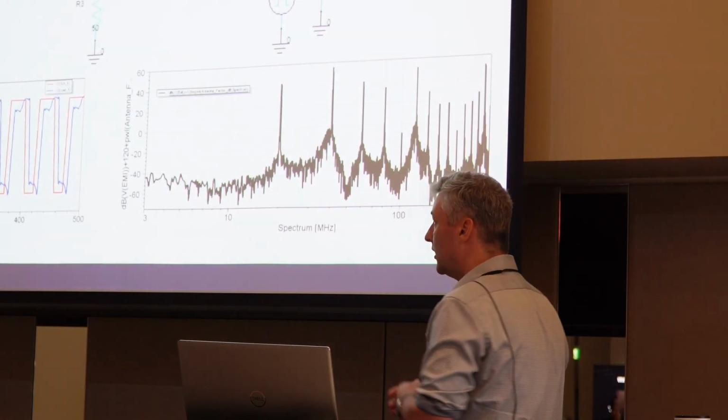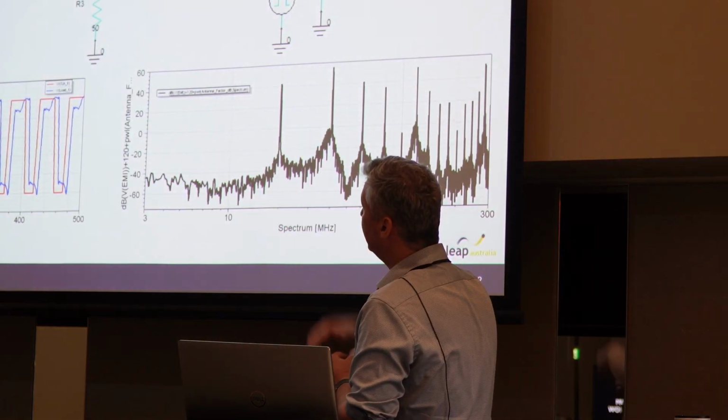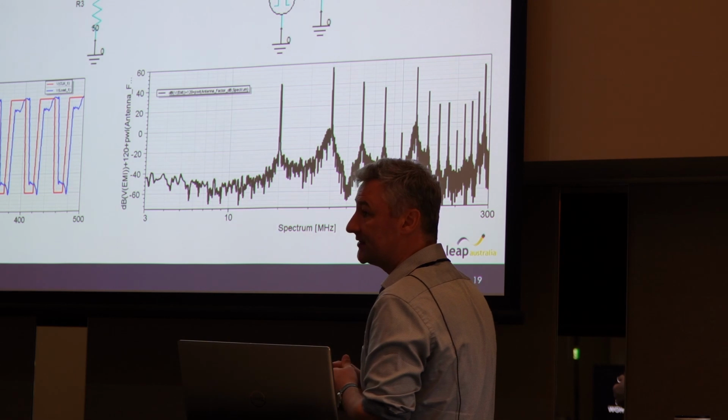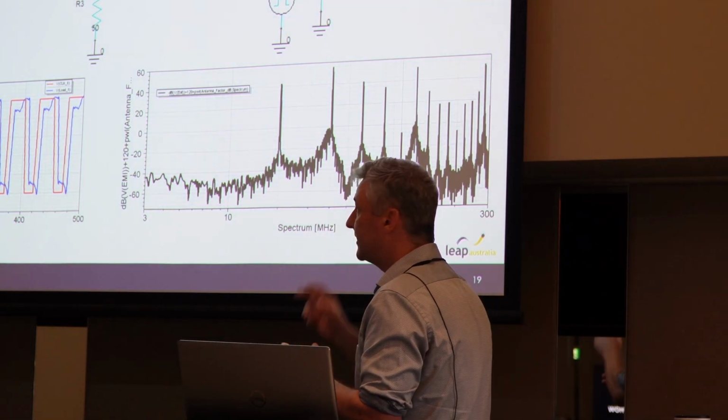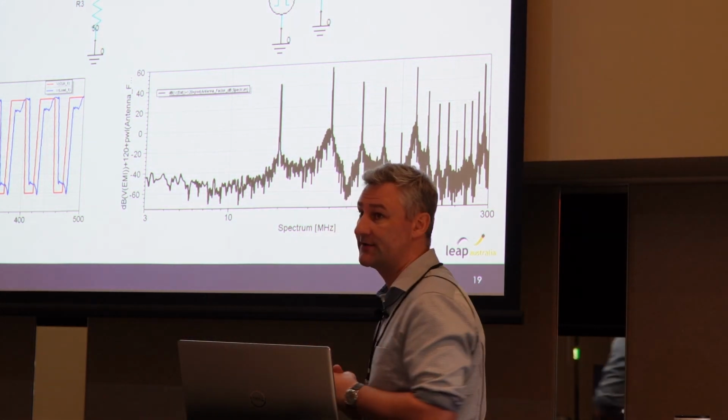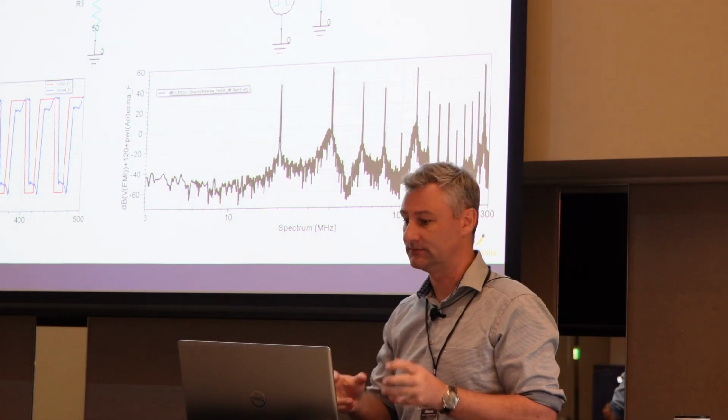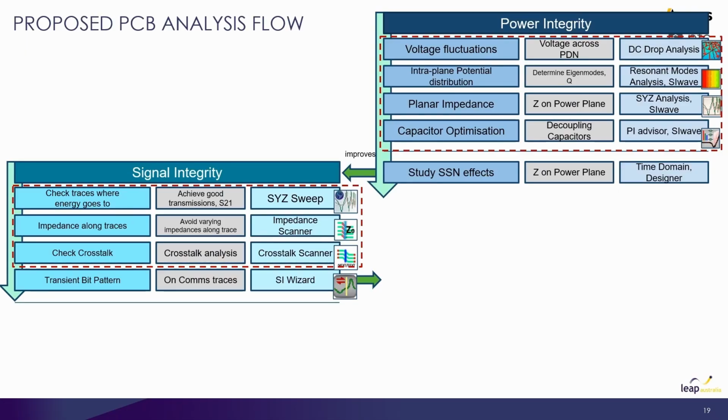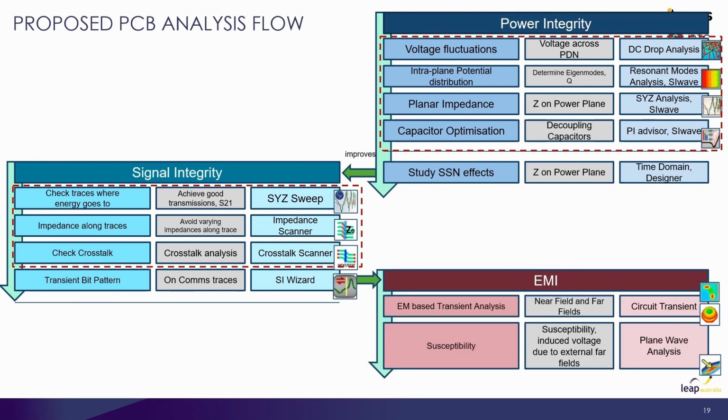So of course you see all the coupling happens in that HFSS project file that we have embedded into our circuit, and the circuit then drives everything. So that's a little bit our proposal, how to go through PCB analysis and make sure the PCB is pre-compliant before it goes into the chamber and so on.